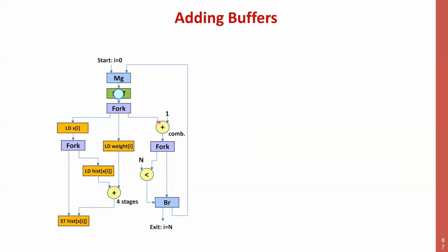At the beginning, we insert a token which says start and says I is equal to 0. It stops in the buffer. It goes out of the buffer on the next cycle, and we expect it to go down the 3 paths, starting in particular from the path that computes the new iterator. We want to go down there and back as quickly as possible, because this will trigger the beginning of the next computation for the next iteration. So let's see what happens. It goes down, and it does exactly what we expect. All this is combinational, so you've seen that the token has gone through and finally came back to the buffer.